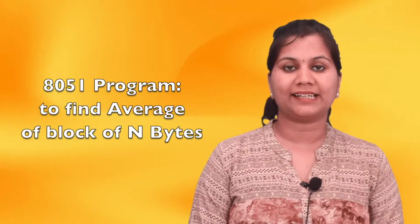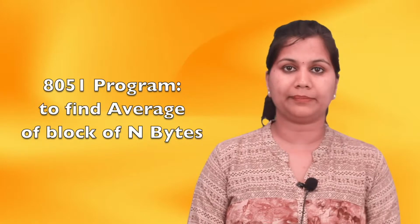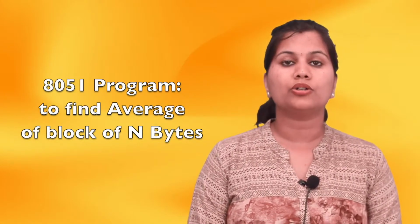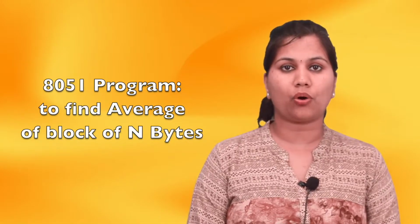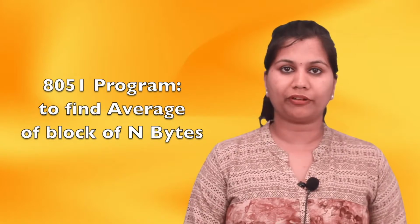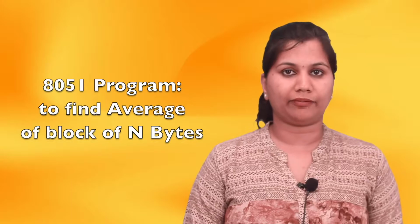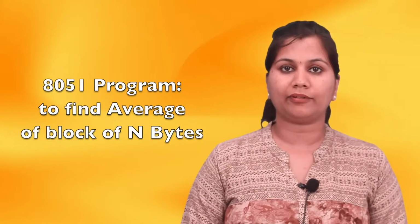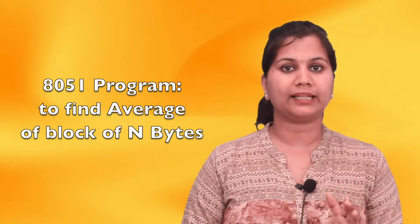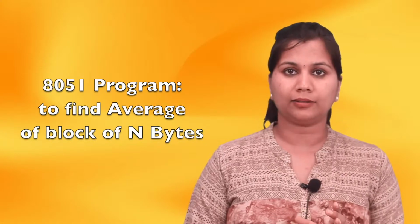Hello friends, in this video we will write a program in the assembly language of 8051 microcontroller to find the average of n numbers. We are given a block of n numbers and from those numbers we have to find the average. Now how do we find the average? We first get the sum of those numbers and then divide that by the total number present in that block.